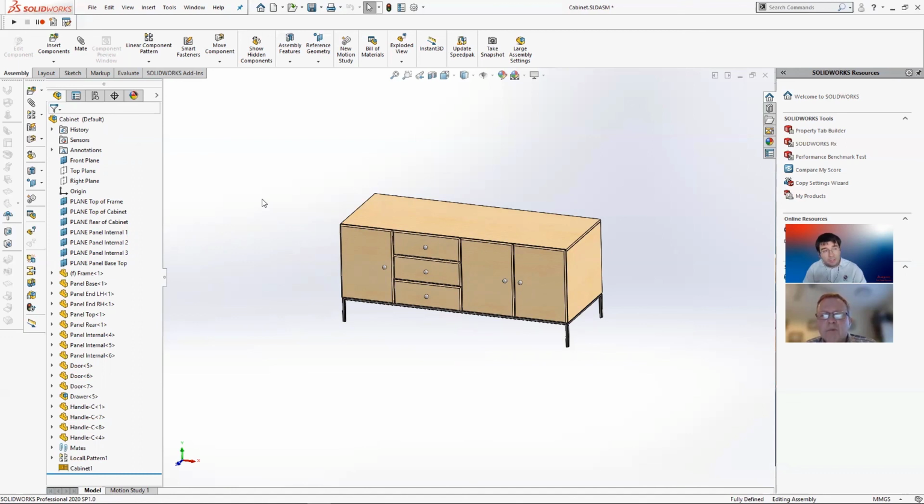If you're building some simple automation, macros are still good, I would say. But if you want to build something a bit more sophisticated, something more long term, especially if you know you're going to run updates later and change your tool, I would definitely recommend going with SolidWorks add-ins, and those are way more stable and sophisticated. Excellent, thank you. That was absolutely amazing, Artem. Thank you for that. Thank you, Bill.